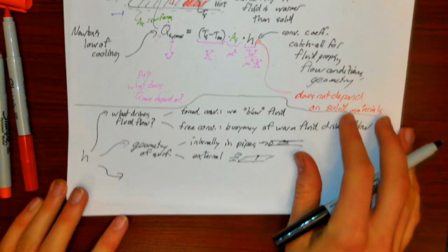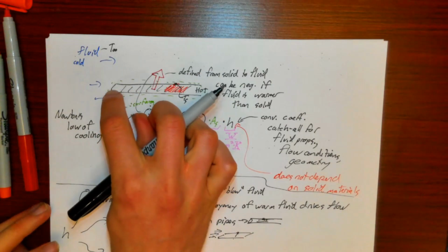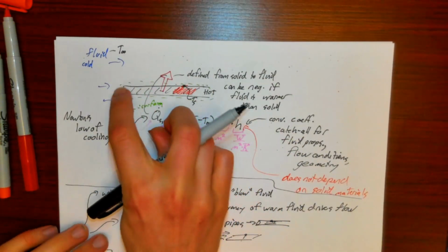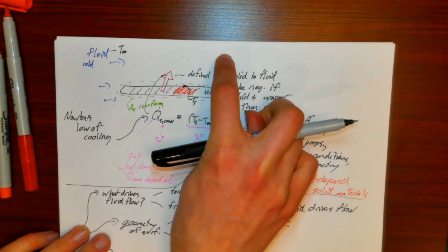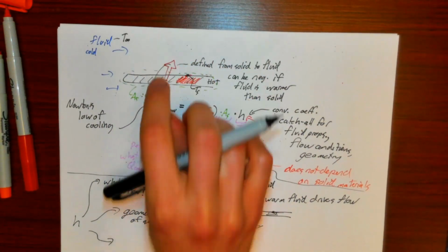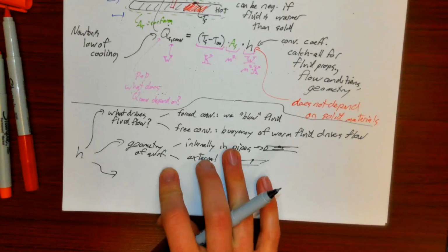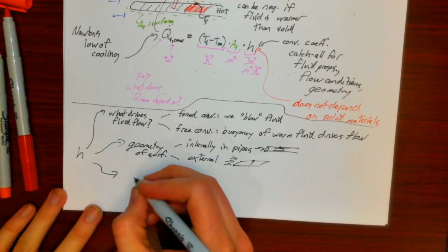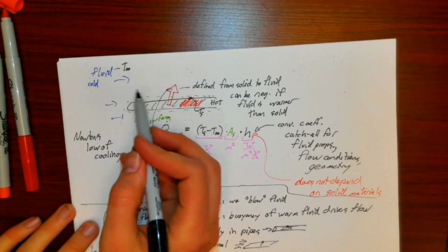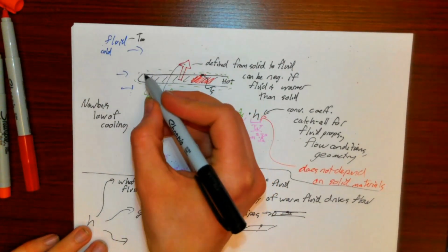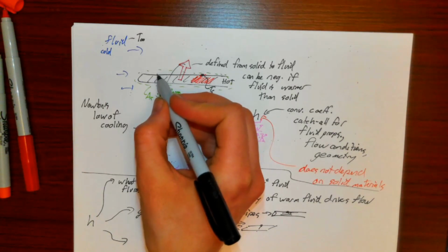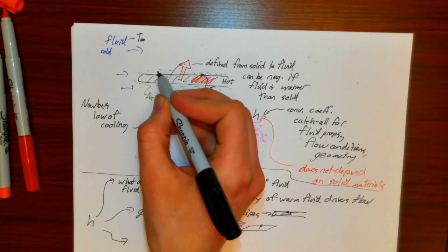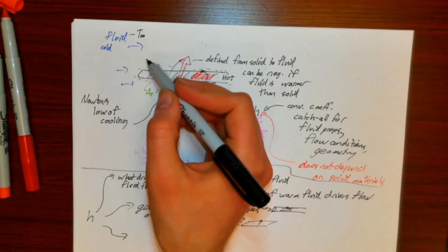H also depends on what's going on in the fluid. And we can imagine, one of the most important factors in terms of how this fluid can carry away heat from the solid is whether the flow is laminar or turbulent. So what goes on here? Well, if I picture fluid flowing past something, there's usually a boundary layer, where the flow transitions between zero flow right at the surface up to whatever the fluid is doing externally far away.